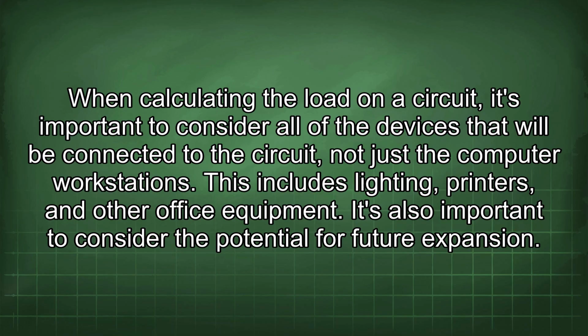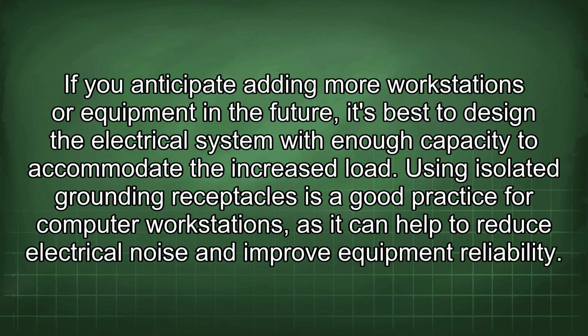When calculating the load on a circuit, it's important to consider all of the devices that will be connected to the circuit, not just the computer workstations. This includes lighting, printers, and other office equipment. It's also important to consider the potential for future expansion. If you anticipate adding more workstations or equipment in the future, it's best to design the electrical system with enough capacity to accommodate the increased load. Using isolated grounding receptacles is a good practice for computer workstations, as it can help to reduce electrical noise and improve equipment reliability.